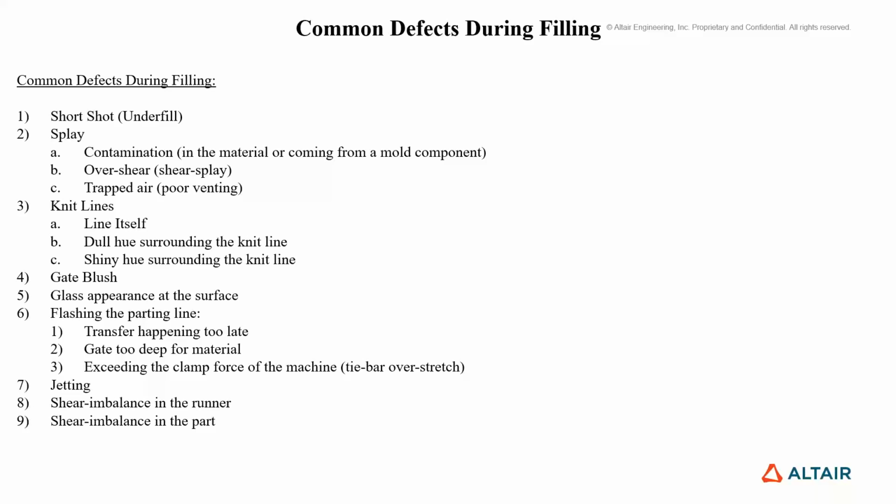There was, however, when we backed off and did a series of short shots and worked it backward, what we found was actually there was trapped air. So there was a failure to vent, and what happened was the bubble ran along the edge of the part, and as it got near the flow front, the bubble got bigger because under high pressure, that air is well compressed, and as it runs along the edge and gets to softer and softer skin in the material, all of a sudden the bubble gets bigger and bigger, and pretty soon it's inside the melt because it just bubbles its way into the melt along the edge of the tool.